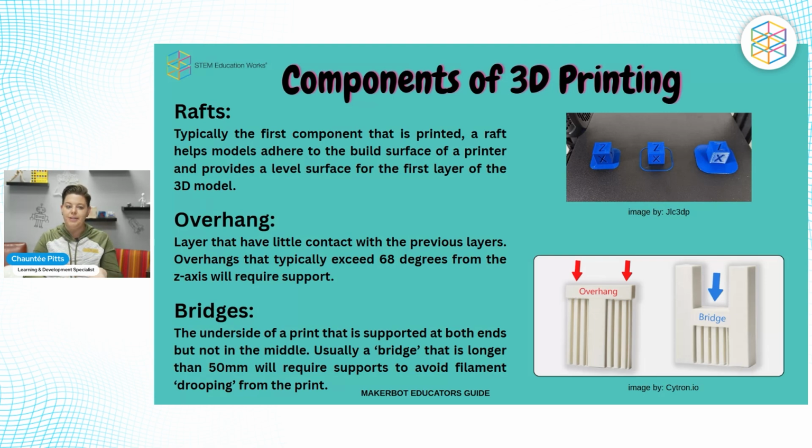That's absolutely true. Sometimes that filament can be wasted because we're getting carried away on using a raft, even though we don't need it. There's a spray out there, made for 3D printing, that I've used and that has been great. I wish I had it with me. I should have brought it. If you're interested, we don't sell it, but I got it from someone who uses it with their MakerBot. And it's been kind of a godsend when things are just not sticking for some reason. I know people have put down tape and then pulled the tape up and it sticks better for that. But honestly, that can be the most annoying, when your print is not sticking to the bed.